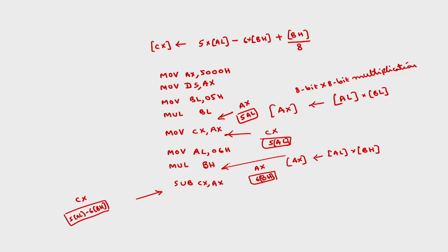Okay. This division by 8, or division by any power of 2, can be performed by simply using shift, with no need of using the division operation. Basically this is shifting by 3 bits to the right. For example, take 100, which is 4. If I shift this to the right by 1 bit position, what happens?